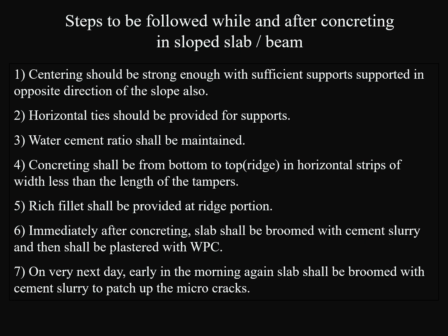Ridge fillet shall be provided at the ridge portion. Immediately after concreting, slab shall be broomed with cement slurry and then shall be plastered with waterproof compound to cover the micro cracks developed due to shrinkage. On the very next day, early in the morning, again slab shall be broomed with cement slurry to patch up the micro cracks.